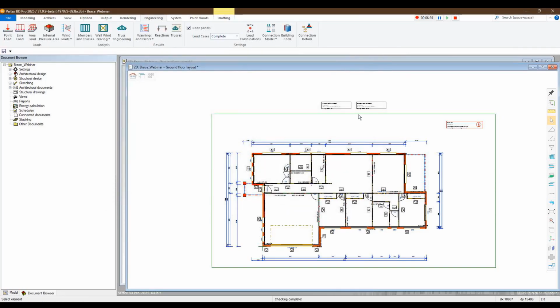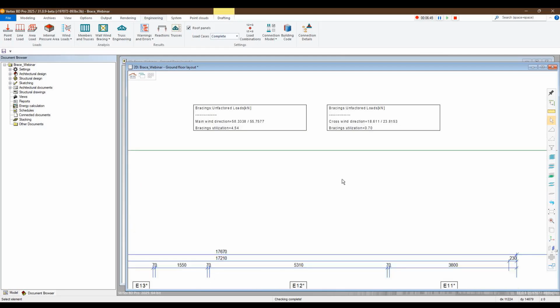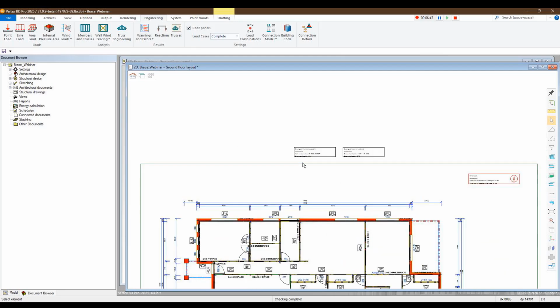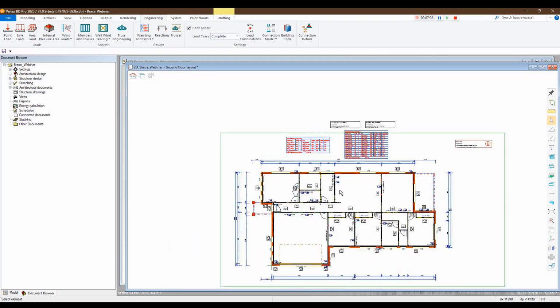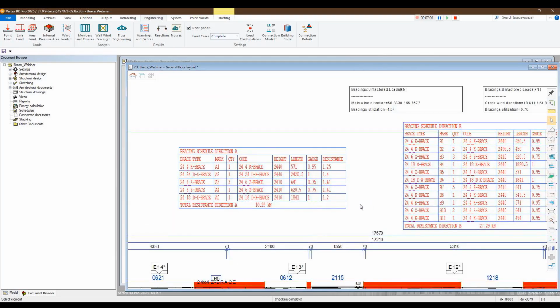And when you do that, you'll get this bracing information here so that you're aware. And then once you do that, if you come back to your wall bracing here, you can go add labels and schedules, which is basically just adding exactly the same information that we added previously. So it'll put all your labels there and it'll give you your information.